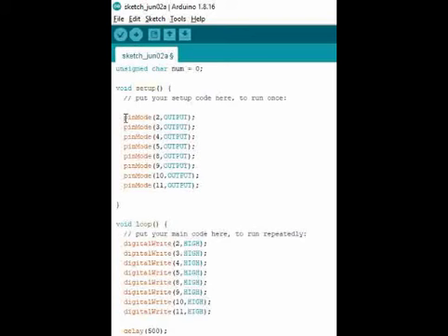That's why you set your Arduino pins as outputs, and once a pin is an output and we give 0, the pin sinks the current. You can see 2, 3, 4, 5, 8, 9, 10, 11. If you remember the table we showed, these are the pins that are used. That is part of the setup.